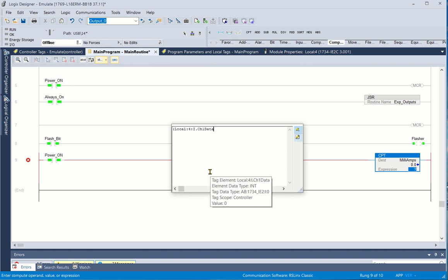And as we're scaling this, we're going to subtract the minimum value of our engineering units, which is 3277, put that in parentheses. So we get the value, subtract the 3277, now we've got a whole value. But as part of scaling, we also have to multiply it by the value we're going to use. In this, we're going to use 20 milliamps as the high and 4 for the low. It comes up to 16, but I'm just making it long form.